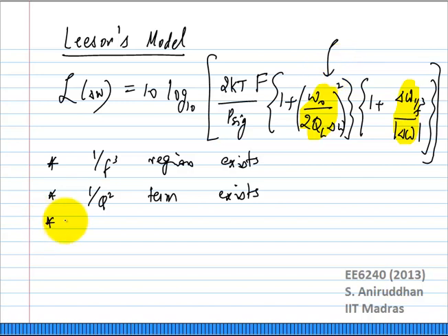What else? Yeah, so these two things are very good. Does it explain dependence on omega naught? Yes, it does. So what that means is I take a 2 gigahertz oscillator, I measure the phase noise behavior. I build a 4 gigahertz oscillator. What do I expect? Fundamentally, I expect the phase noise to be worse for the 4 gigahertz oscillator. So fundamentally, it's going to be tougher and tougher to build oscillators at higher frequencies with the same noise behavior. That is what this also says.